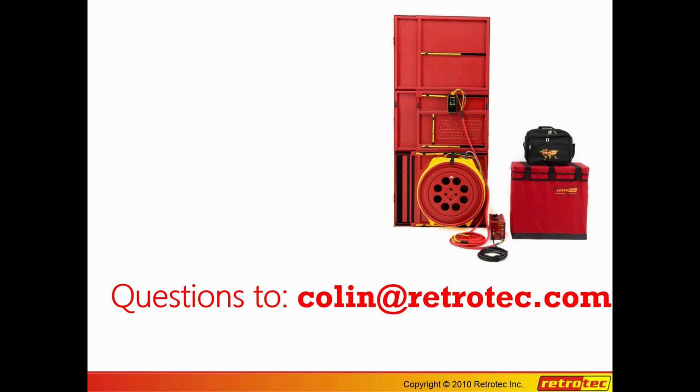So someone was asking, should the PRV be specified before the test so it can be installed and included in the test? Well, one of the reasons for the designer calculator is to figure out whether we have the potential of needing a PRV in the first place. If you're showing up as a tester and there's no PRV installed and they want occupancy next week, then it's a little bit late to start to worry about putting a PRV in there. It really needs to be considered during the design phase and be part of the plans.